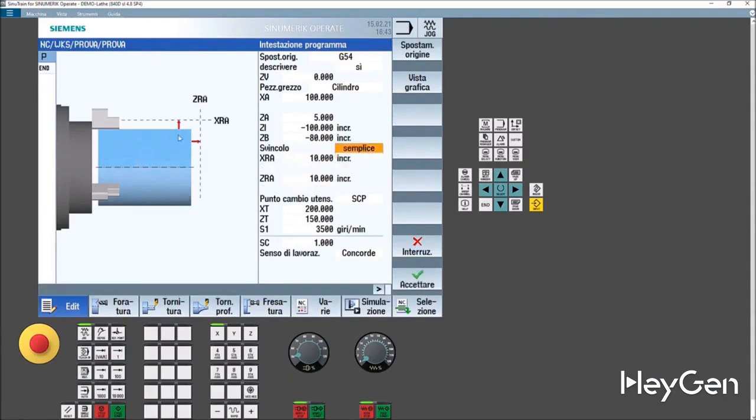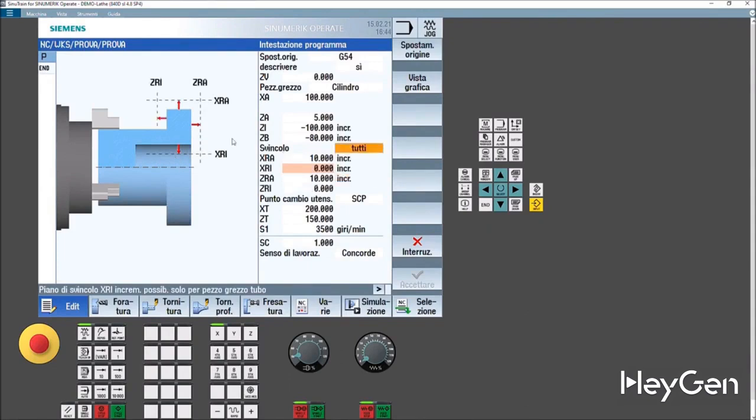What does simple release mean? If we don't have internal processing, then it will only release in these two directions. Expanded release identifies processing. Lift, move, pull. It will recognize a pulling operation. So first it detaches, then goes up, then moves away, depending on whether it's internal or external and how much I release. Here are the values. 10 is a bit low. I went crazy the first few times. If you release only 10, then you're not far enough away.